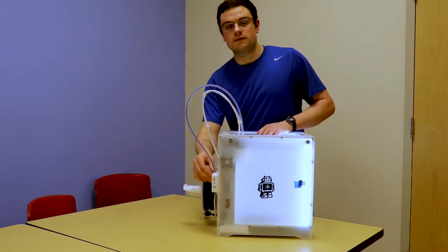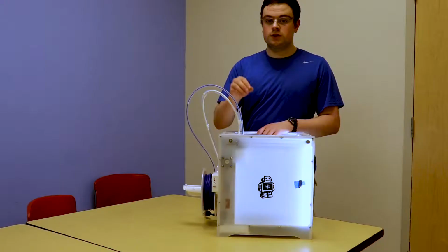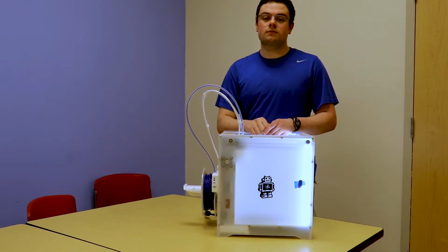This is the motor that drives the filament into the print core. That filament not only prints, but it also acts as a plunger that continuously pushes the filament through each of the pressure zones and is what is needed to overcome the pressure drop through those 3 zones.